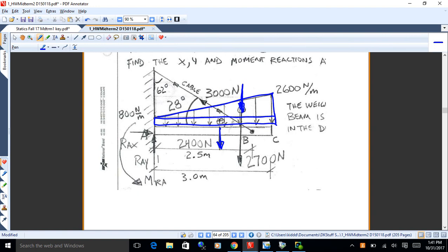All right, now you've got a cantilever over here, so you've got three reactions associated with that. So your actual approach to working through this is not really complicated. It doesn't involve a strategy on what I should do first and second as far as working through the equations. You're just going to apply the three equations there right at the support, okay? The force equations can be applied anywhere you like, they're just directions. But the moment would be applied at the support is usually what I do.